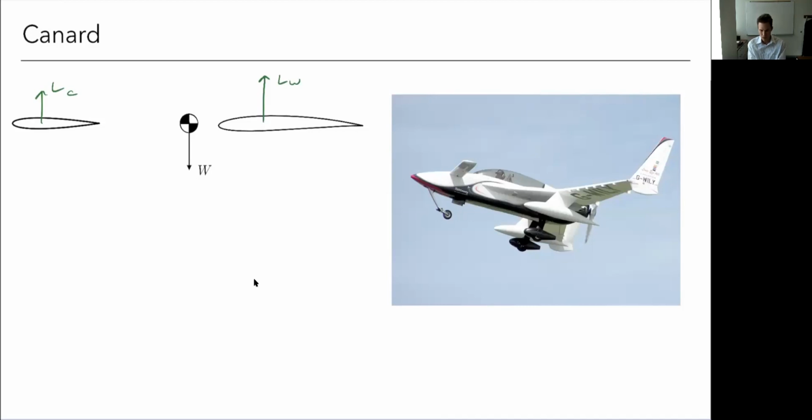In practice, though, it tends not to necessarily come out ahead aerodynamically. It's often just a wash, and depending on how you do it, it could be beneficial, but it could also be much worse. The reason is that with the canard, we still have to keep our center of lift, aerodynamic center, behind our CG, so we can't put the canard too far forward. And because it's not that far, it needs to carry a sizable amount of the lift. So this term here is pretty big. Whereas for a tail, pushing that further back is not going to bring our aerodynamic center forward.